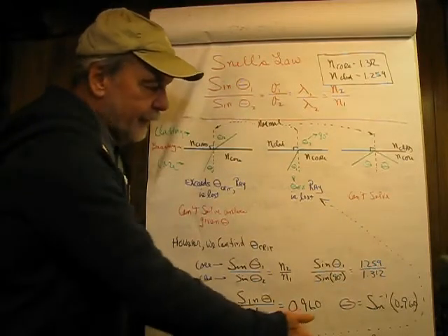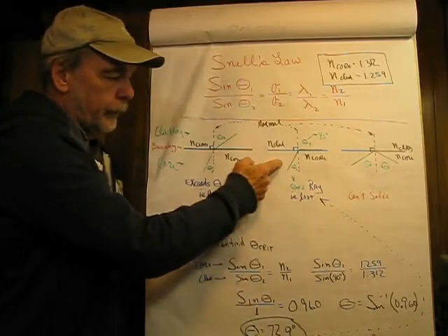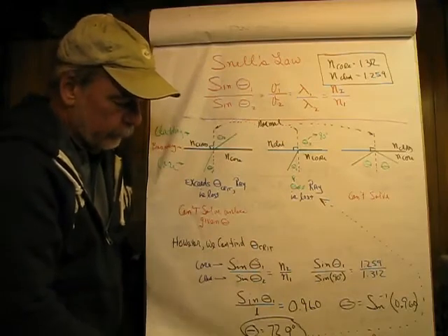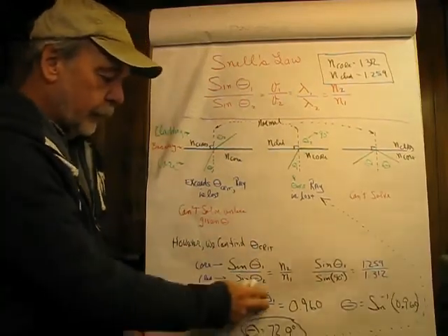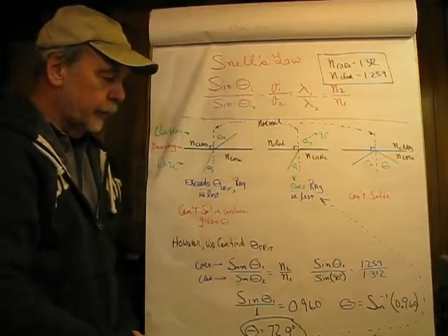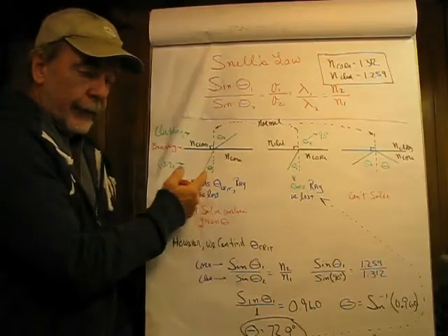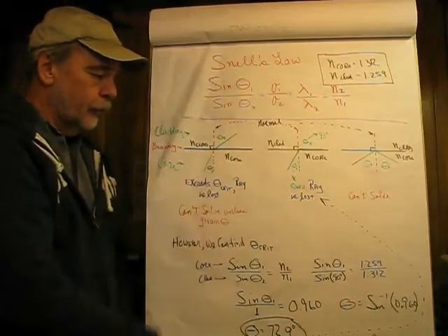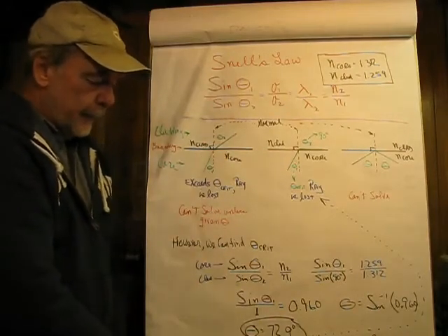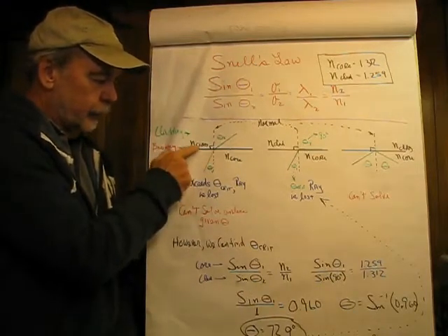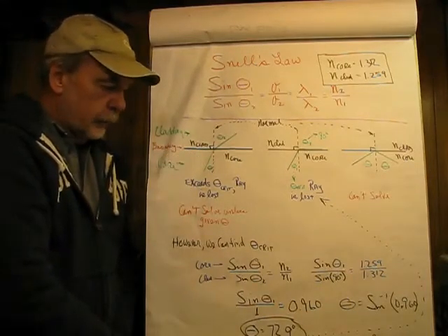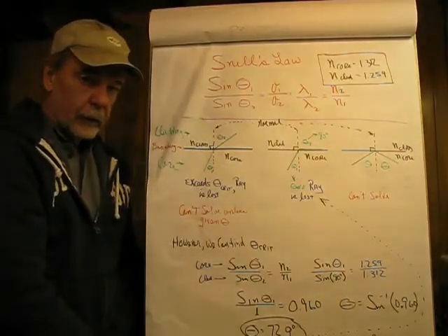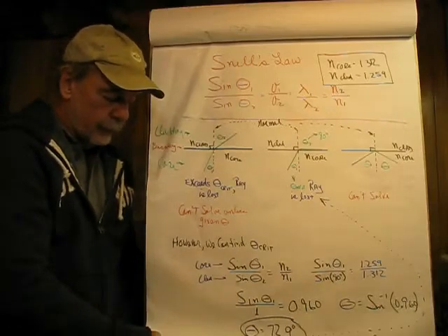This is not to scale here, so this angle would really be considerably larger. Okay, so that's the way you know the critical angle. When you know the critical angle, anything less than that is going to cause the ray to disappear into the cladding, and anything greater than that, the cable would feature total internal reflection, which is what we want. So at least we know what the boundary is for a given cable.